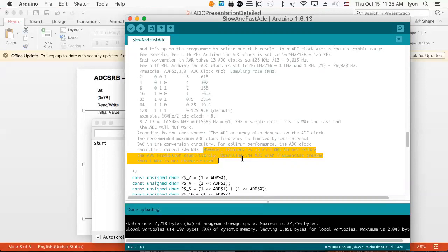As far as I know, it could be down to 9 bits, 8 bits, 6 bits. Take your pick. Who knows? And "not characterized" means they don't really care what you do if you want to do that. It's not going to blow anything up, but don't expect it to give you a full 10 bits worth of accuracy.